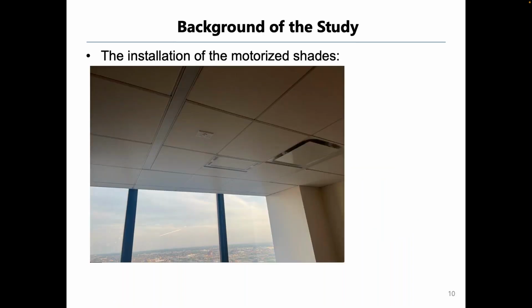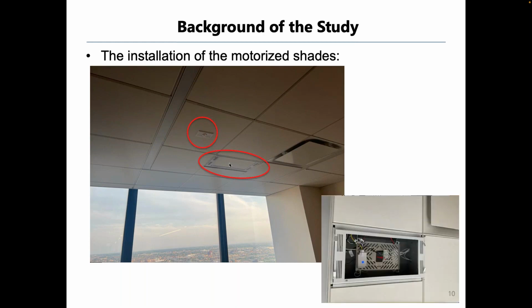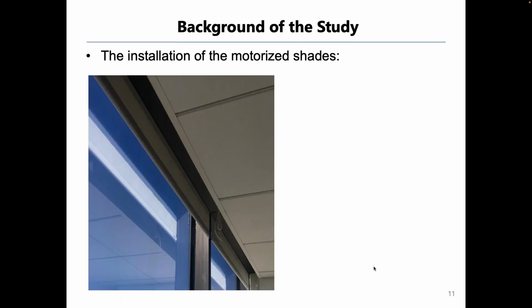If I want to show it in the real application, you can see this is the occupancy sensor. As you can see, the light is orange, meaning that we are almost in that space. Otherwise it would be green. Take a look at the ceiling tile here. This is the one added by the electricians. If you look inside of that, all the controllers that I showed in the previous slide are included here. This is the 0 to 10 controller. This is the Amatis controller, and the wiring is the communication for the shades.